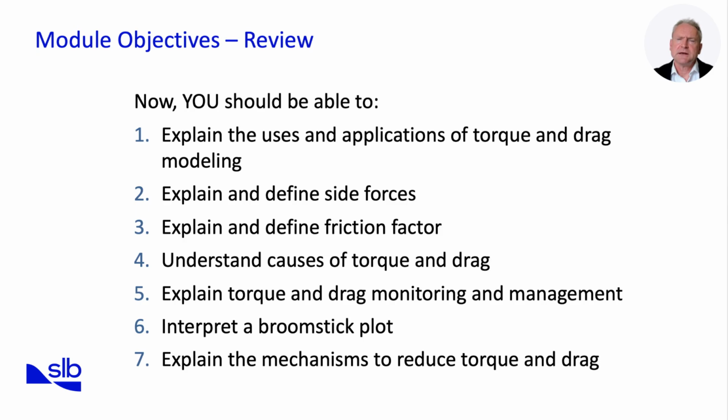We emphasized that measurements must be taken consistently at every connection, after inclination changes, before casing runs, and using steady movement at constant speed. Next, we introduced the broomstick plot, showing how measured hook loads compare to modeled values. We interpreted examples of poor hole cleaning and casing running, demonstrating how divergence between actual and planned curves provides immediate diagnostic insight. We then covered drill string design, breaking the well trajectory into 6 sections and discussing the function, desired characteristics, and design considerations for each.